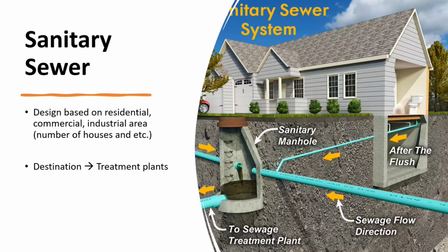And if that happens, we're going to have backup in the sanitary system, and that backup will continue and go up. And if any basement of any houses, like the one that you can see here on the right, is lower than the hydraulic line of the sanitary system, then we're going to have basement flooding. And each basement flooding costs tons of money just to clean, because the water that is going back into the basements is not clean water, it's sanitary water. So yeah, that's not pleasant to happen.